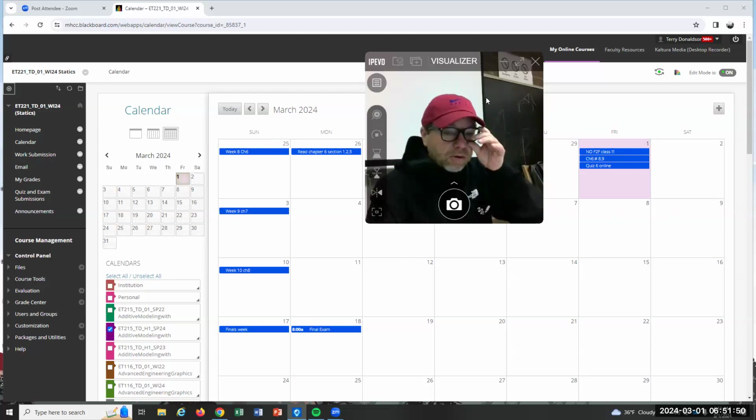So you can always work a problem or attempt to work a problem by summing forces in the X and the Y. That works on most of the simpler problems. The other day we worked one that had to be two equations, two unknowns. The other way to work that problem would be the way I'm going to show you now with the resultant friction force. So it's just another method that can be used.